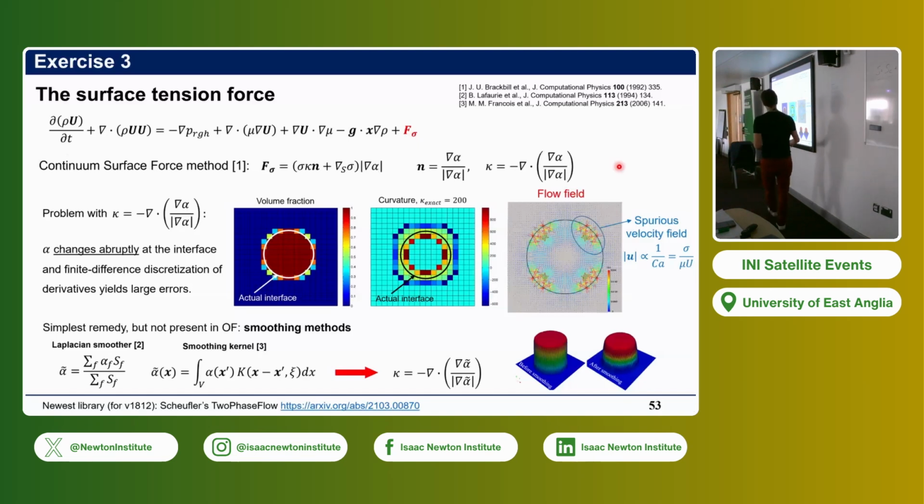So I would call this one the ultimate library for OpenFOAM, which is not in the official release, is available on GitHub, and is a fantastic library to do two-phase flows. There are also some publications where they compared Basilisk to this library for the typical case of a bubble rising in a fluid, in a case where you have a low viscosity fluid and the bubble rises, making some helix, and it can achieve the same results as Basilisk. A bit slower because there is no balancing being implemented, but it could be a good alternative.